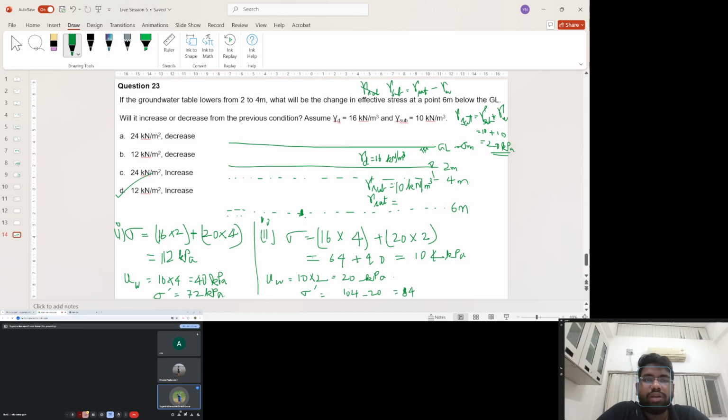All right. So this point has several interpretations. Now the effective stress which we are calculating is the stress acting on the soil at that point, right? Now if you consider a real life scenario where you are drawing water from a well, or there is a sudden drop down of water level, that is the most critical condition which we consider for analysis or design.